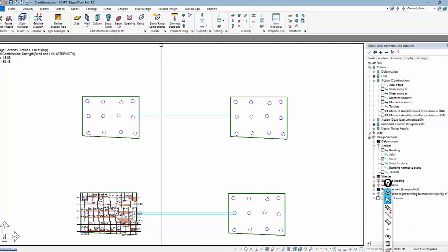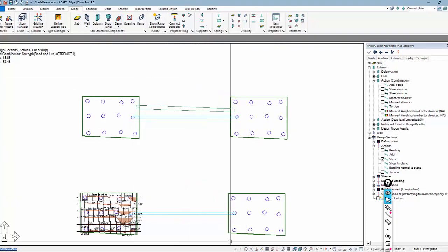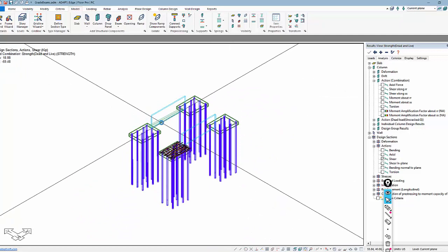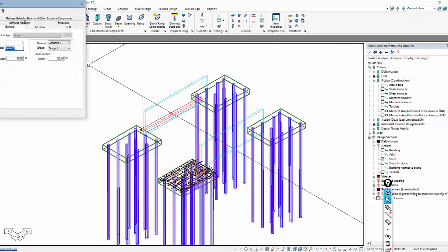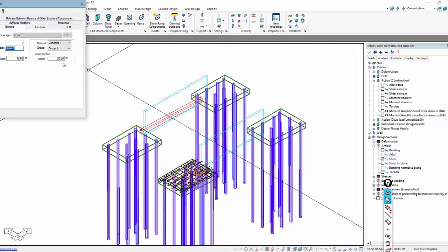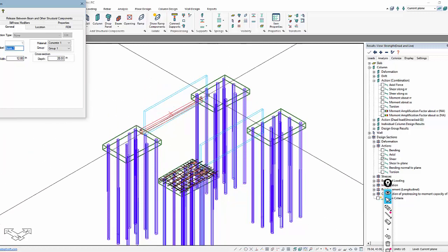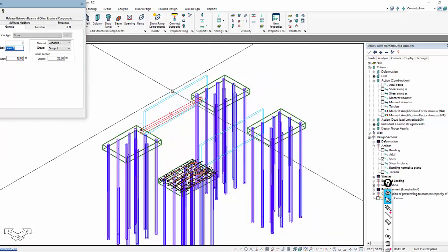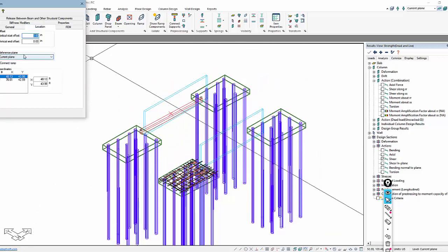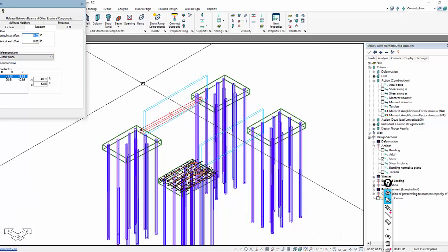okay, we'll go to model. Let's just put a beam along the side of this. If I model a beam along this path, you can see that beam can be shifted vertically. I can create an offset for the beam, so I could create a depth of the beam that's quite tall. It's 120 inches in this case, and then I could create an offset, but that beam still is only connected to one level.